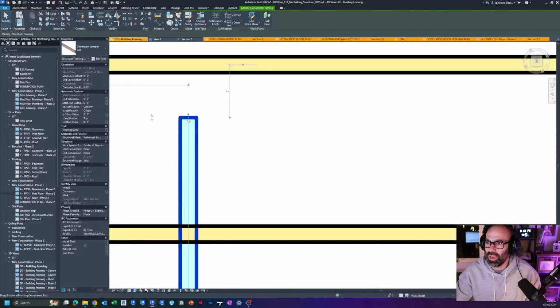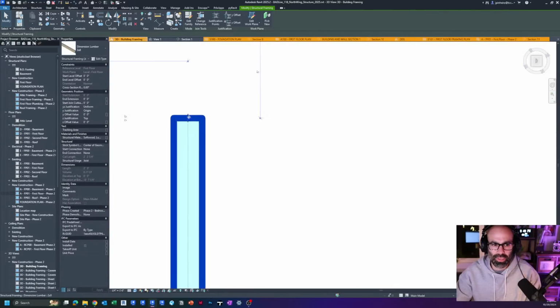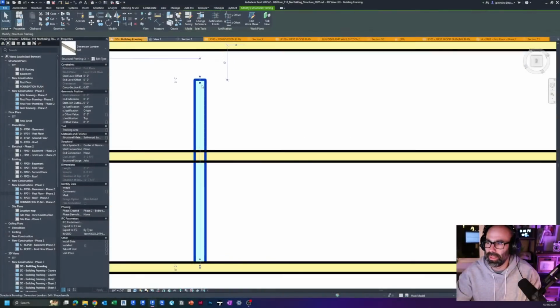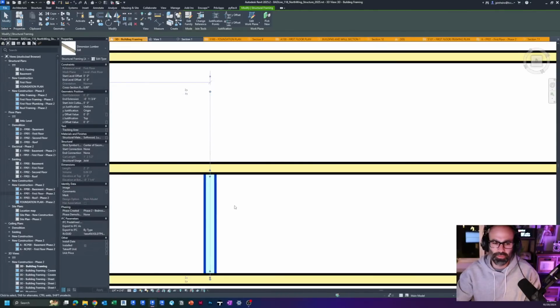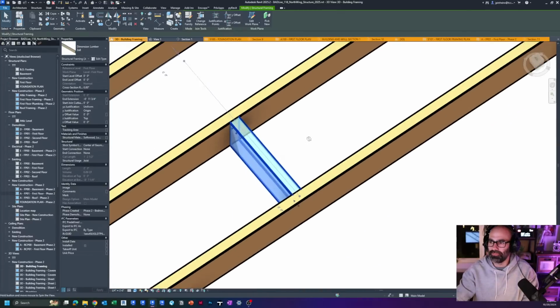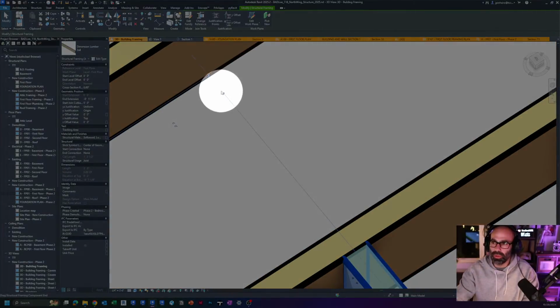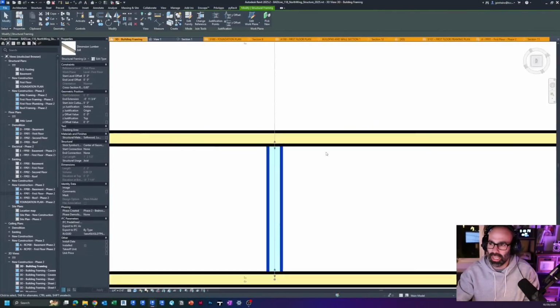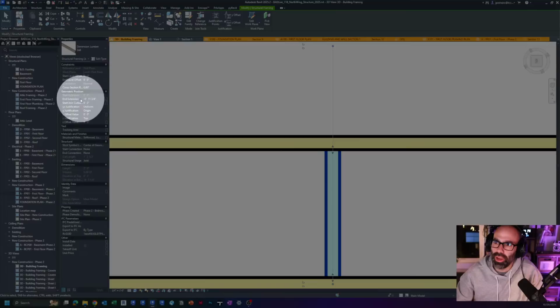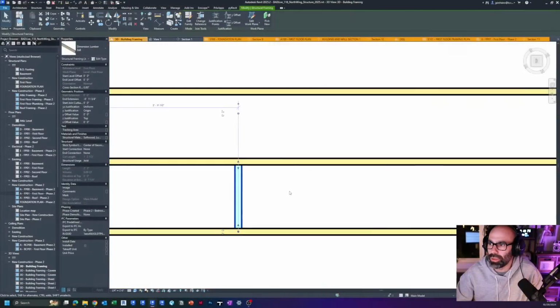Notice how there's a blue dot and there's an arrow. Hopefully you guys can see that right at the end here. Okay. If I move the arrow, so I'm going to try my best to move the arrow here. If I move the arrow to here, graphically, this looks fine, right? But you'll notice how there's a blue dot out here and there's arrows back there, right? That's called an extension. And if I look over here, you can see end extension is 11 3/4.